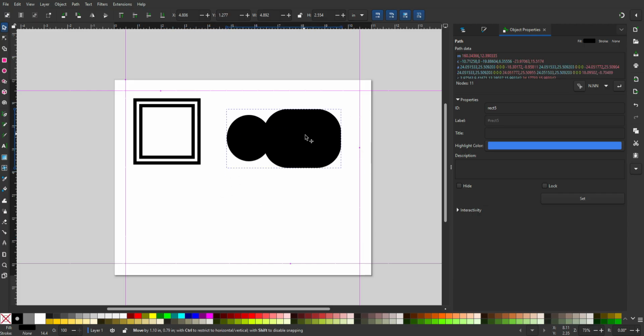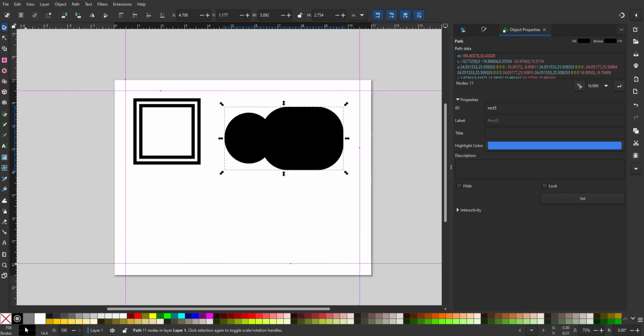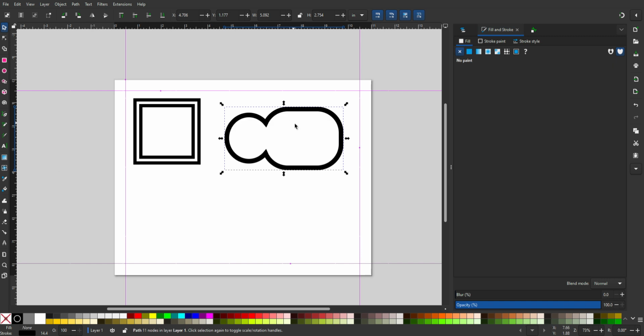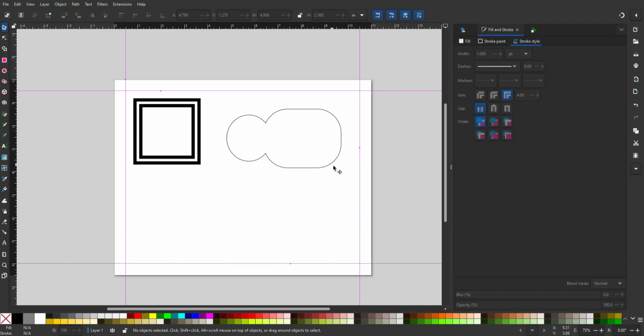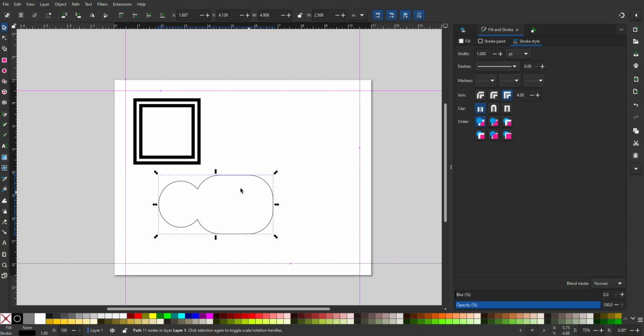So when you're drawing stuff, if you wanted to make a Mickey Mouse head, you could draw three circles and then use that path union to make it one thing. And so all the black is gone in the material, basically, if it was etched. Yeah. This allows you then to make it one point. And so now there's just one vector line for this object. You could cut with that one because it's thin. Yes, if you want to.